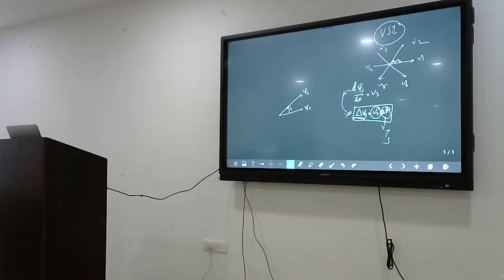See, this is the resultant phasor diagram of the voltage source inverter. Power semiconductor device phasor diagram, voltage phasor diagram. Why? Because there are 6 switches in the voltage source inverter. By using these 6 switches, we are able to produce 6 voltage vectors with different phase shifts. Magnitude is same, length of the vector is same. Only the position is different, right? By selecting the proper combination, we can get V1.